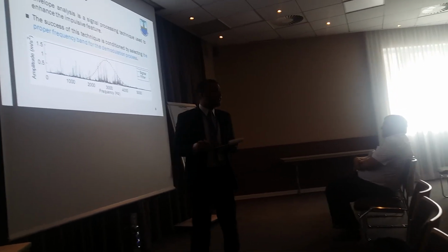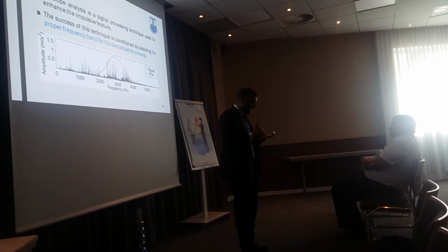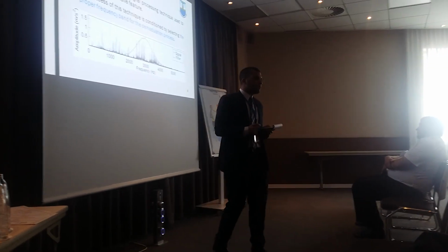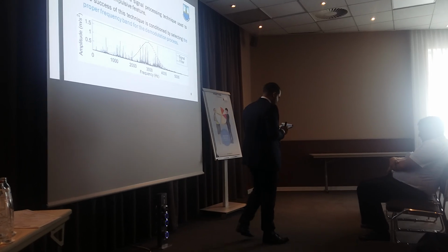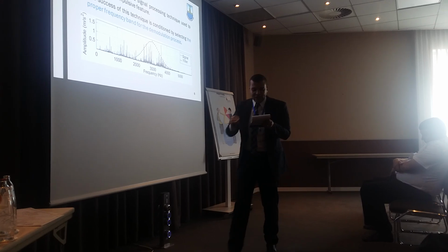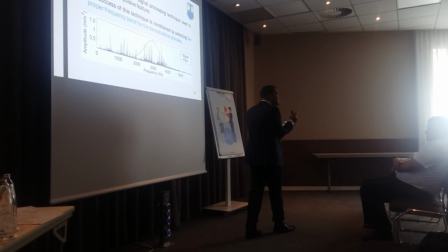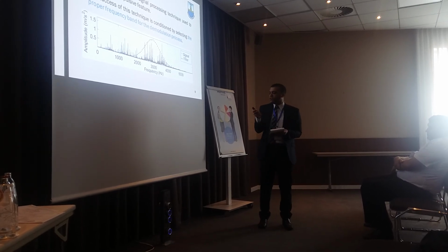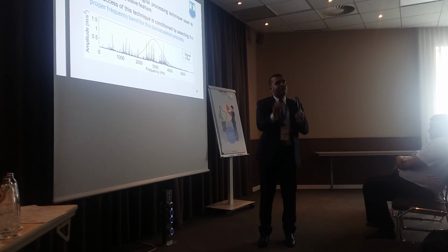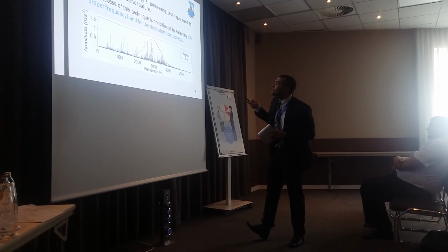Envelope analysis is a signal processing technique which is typically used to solve this problem. Envelope analysis enhances the impulsive feature in the signal by a process called demodulation. The demodulation is based on the fact that the faulty bearing signals modulate the bearing system resonance. However, its success is conditioned by selecting the proper frequency band for demodulation. This is the raw signal in the frequency domain. The useful information about the bearing fault is only in the resonance region here. So we have to band pass filter around the resonant frequency.